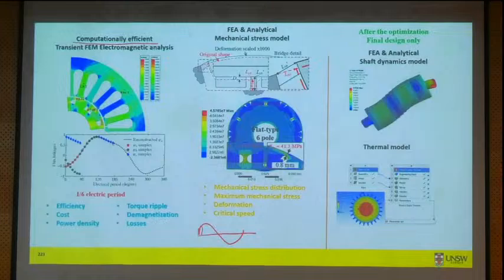So the finite element simply calculates, in this case, only these points. That's the computationally efficient FE. And the rest of the waveform it will predict, or you can extrapolate it. So that's how you reduce the computational time.